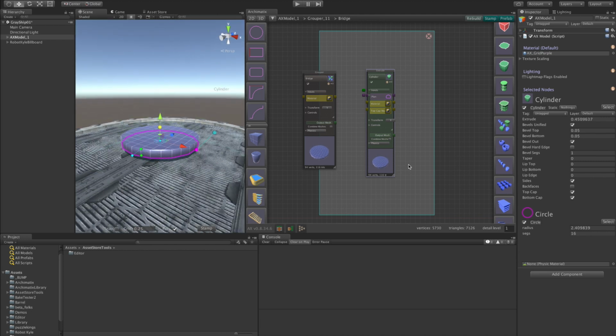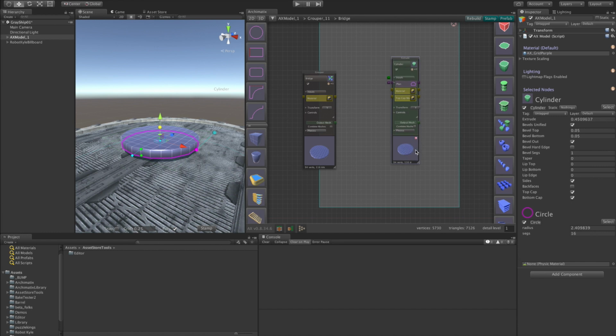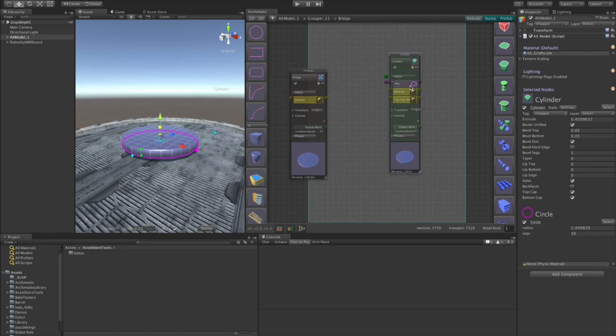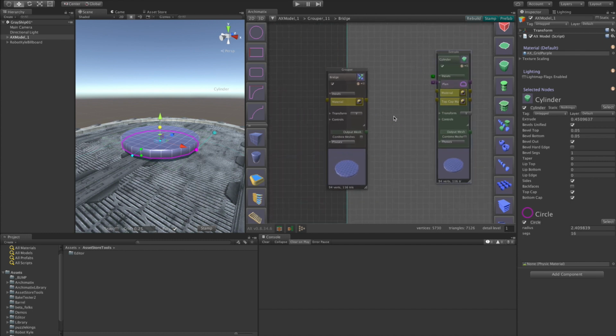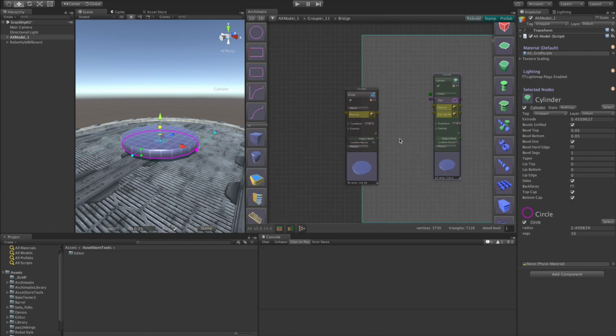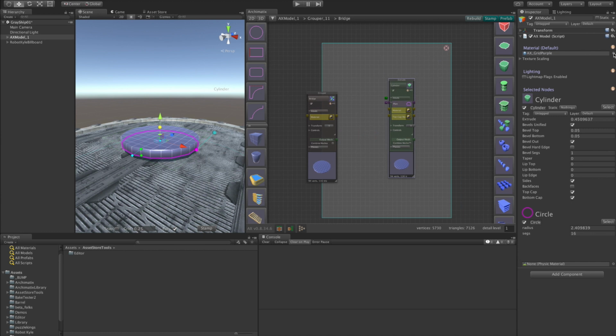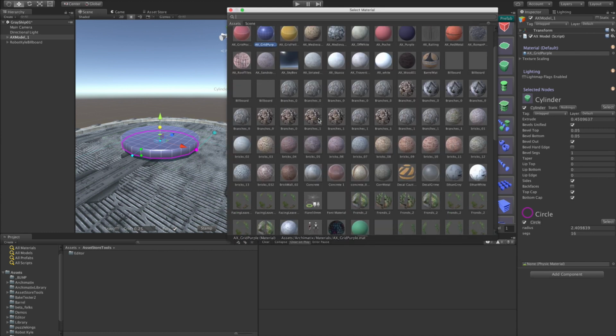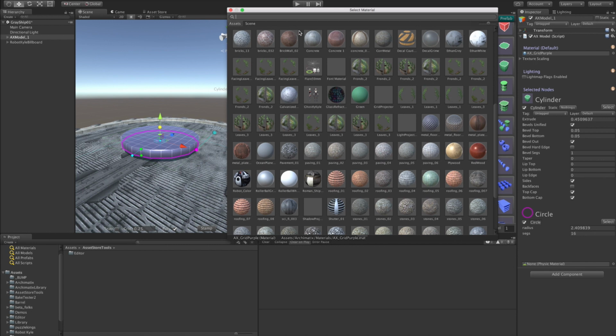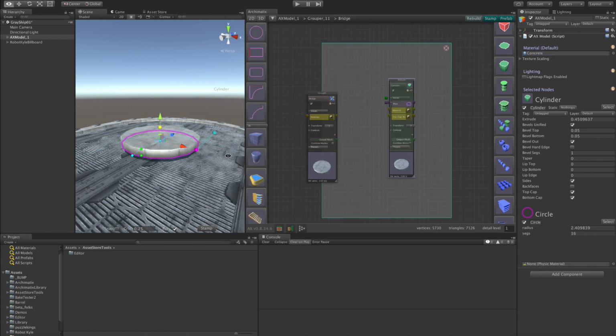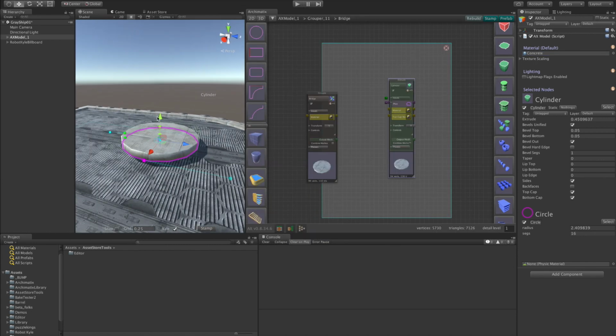and we can begin to adjust it and set its material. We could do this either as a default material for the entire model, a material node that we add to that cylinder, or a material node that we add to the entire group. For now, we haven't really specified a default material for the model, so let's make it concrete. Now, any new object created will have this concrete attributed to it.